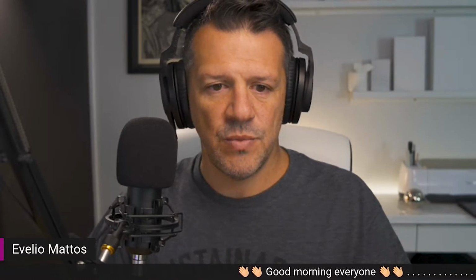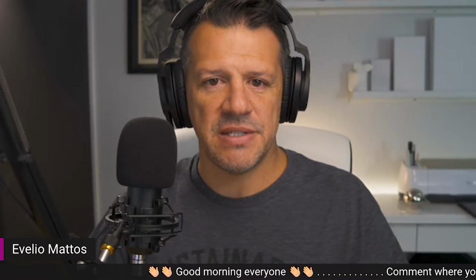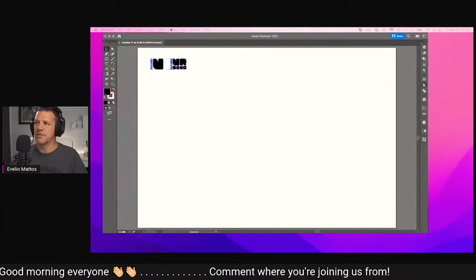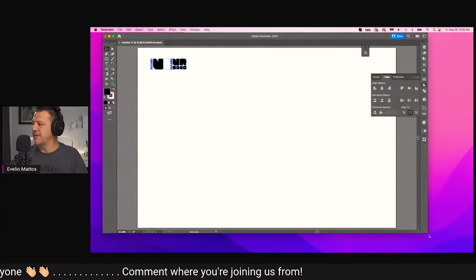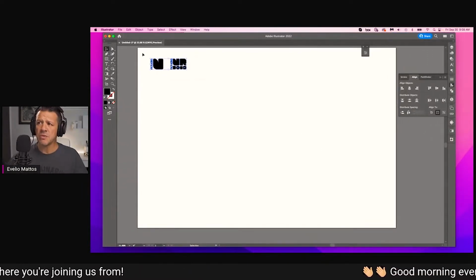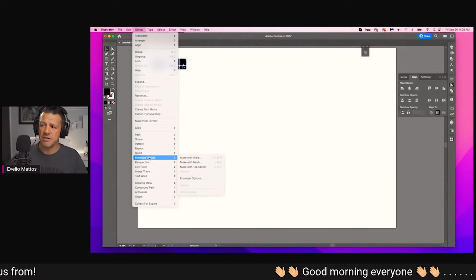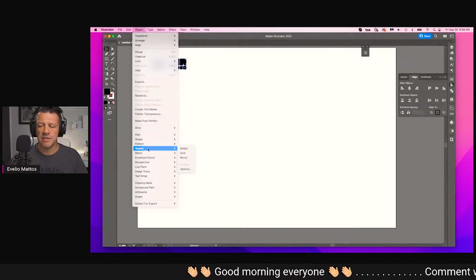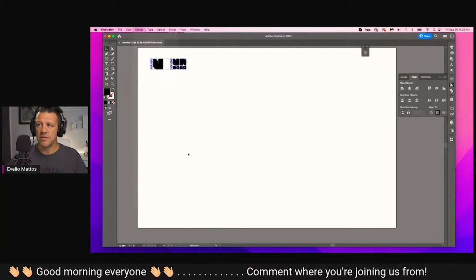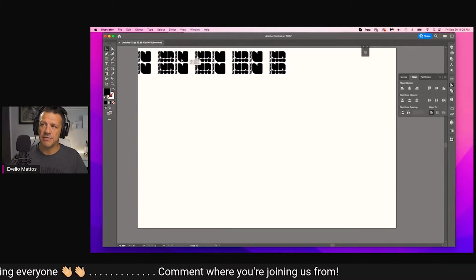We're always working on the fly here, so we have to figure out how best to show you the entire screen. All right, now you can see the entire screen, which means you can see the file, edit, object, all the navigation on top. So we select this, go to Object, scroll down to Repeat. Do we want to repeat it as a radial or grid? For this, you're going to do a grid. So you click on that, and automatically you've got a full repeat happening here.